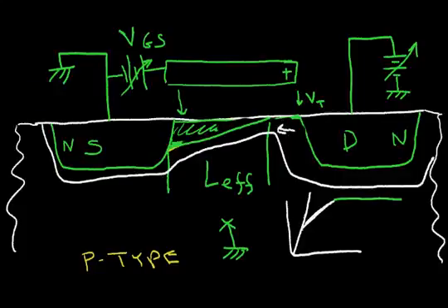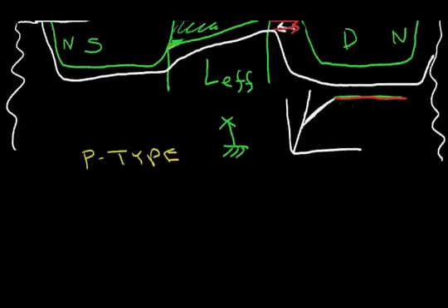What happens is these electrons are attracted to this drain region. So they just shoot across this depletion region in such a way that we have more or less a constant current source. And there is an equation that we can use to describe this part, this constant current region.